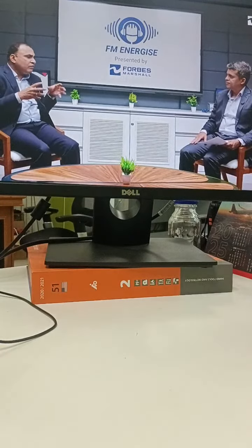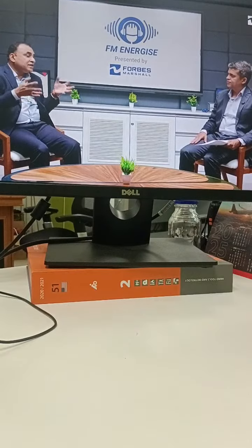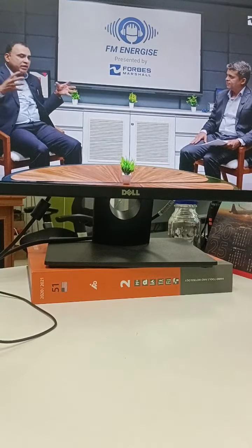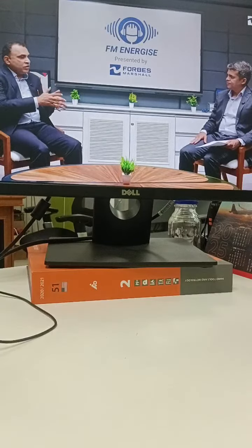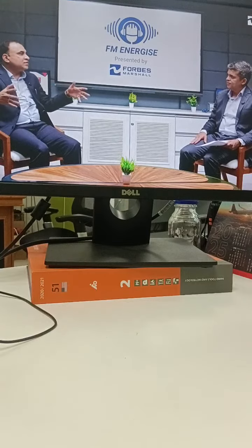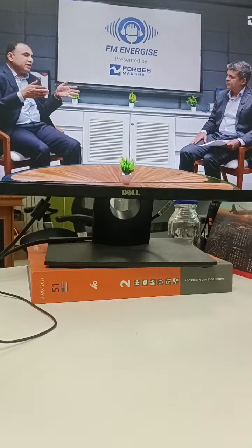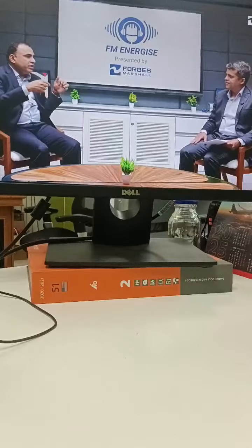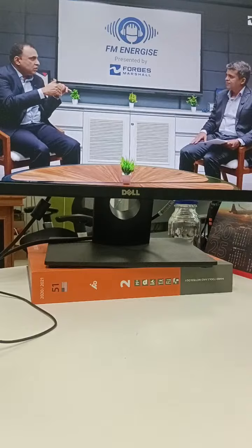When we do all that, various applications come into play. Take a turbine, for example. A turbine is very large rotary equipment, and when you are mounting sensors on such large rotating equipment, various types of sensors come in. A turbine has a very large casing and a rotor shaft rotating inside, and you have to do shaft vibration monitoring. For radial shaft monitoring, you have to use eddy current sensors, non-contact probes.